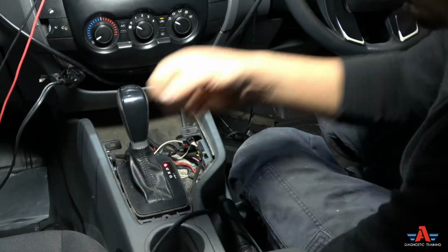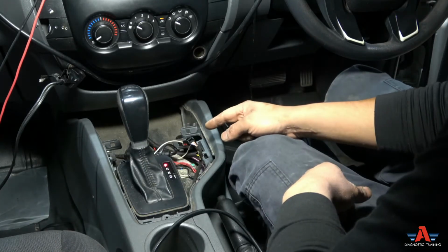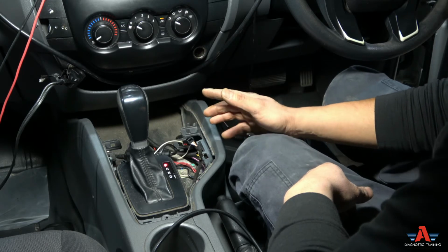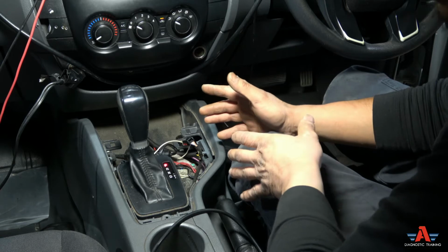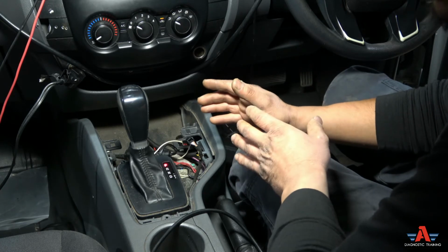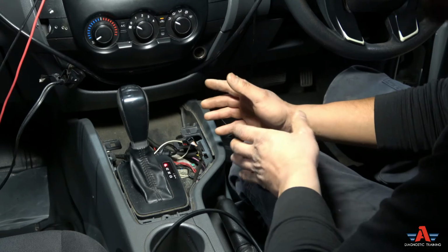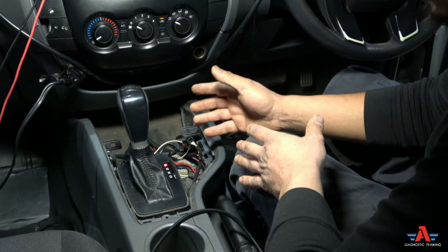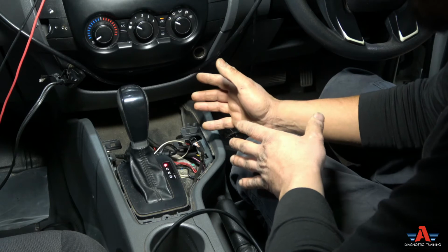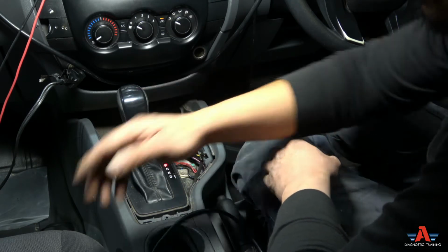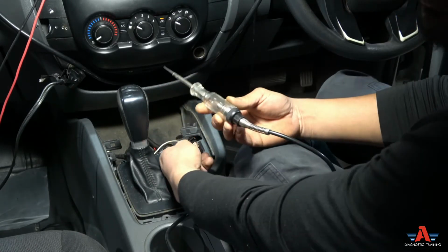Now computer switches are going to have power, the 12 volt, sometimes 5 volt. They can work with 12 volt or 5 volt. A lot of the time they will send 12 or 5 volt bias voltage, or for that regard it could be any voltage level, it doesn't matter, but most I've seen is 5 volts and 12 volts. So if you put your test light on, the test light is too heavy.